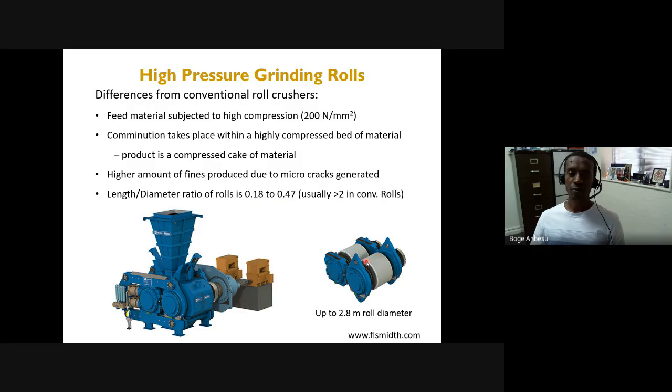And because we make them very large, they actually have a very high nipping energy. So this could be compression of around 200 newtons per millimeter squared. So this is a very high compression force applied to the rocks. So instead of just compressing them, we actually have a very high impact force, excessive compression, if you like, which then smashes the rocks and produces lots of fracture inside the rock.